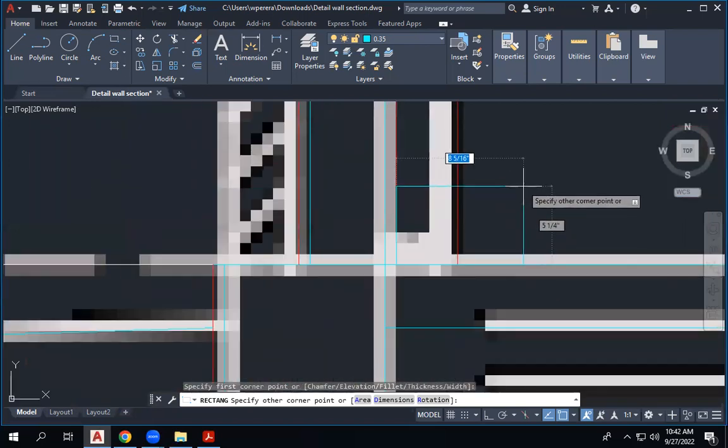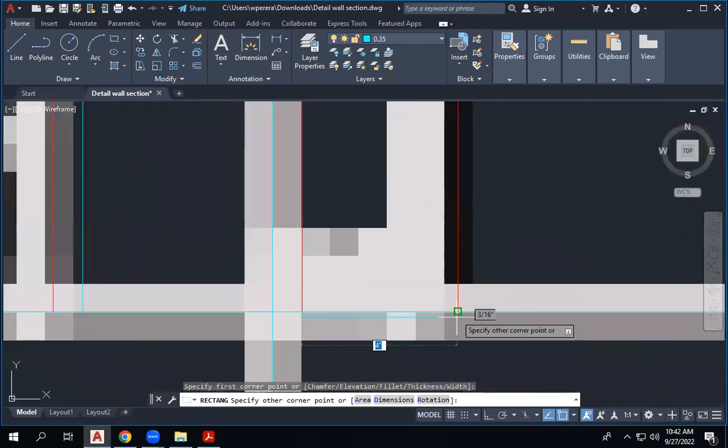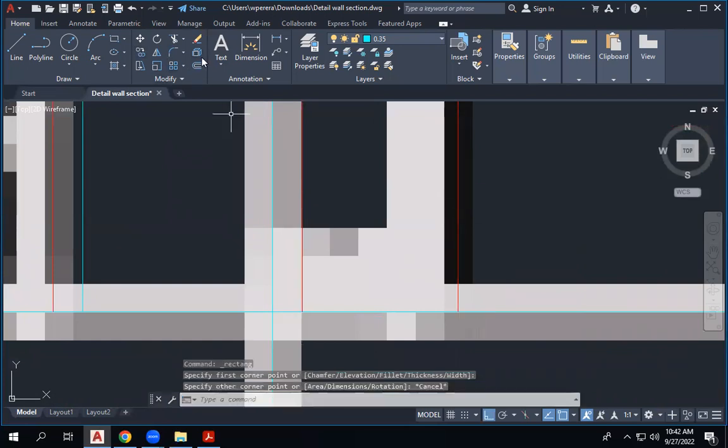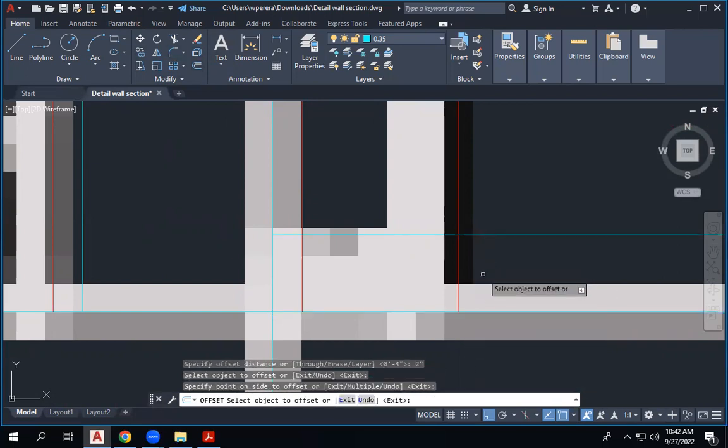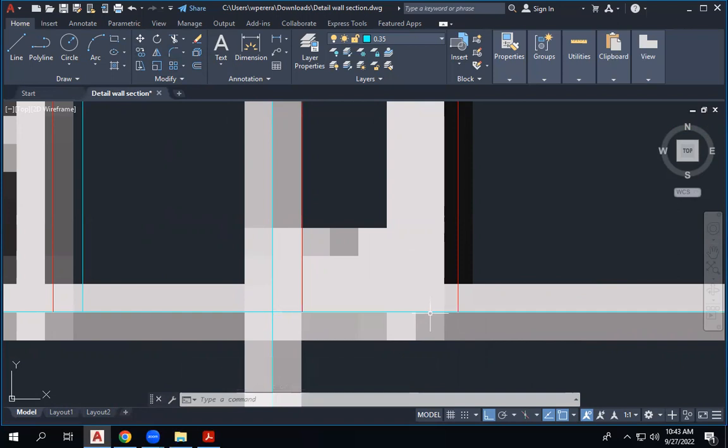You can also just use an offset, no need to draw a rectangle. You can just offset here by 2 inches. But I was trying to make it a rectangle because then you can have a different line thickness for that section because it's been cut at this point. Here I used 0.1. You can have that timber section as 0.2.